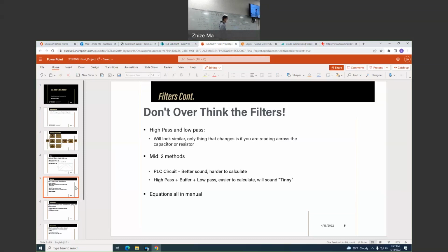Also, one other common mistake I remember from last semester is, even though it's very clearly shown and explained, you need low pass, buffer, then high pass. Lots of people, for whatever reason, will not put in the buffer. If you do that, you get a lot of crosstalk and loading between your low and high pass. So if they're going that route and having issues, another thing we can double check is that they are actually including the buffer.